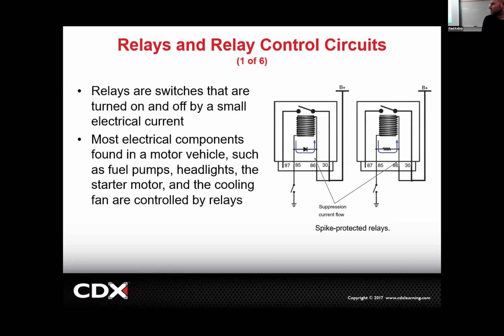This allows the electrons to leave. If you open up this ground, the electrons can't make their way back there, so it'll make a little drain, but it'll make it so it doesn't kick back and spike the ECM. This is especially important once we go to computer control. Cool? Okay, go ahead.